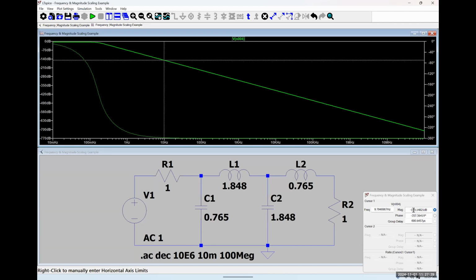So we're going to talk about Butterworth filters, which are used in applications where we don't necessarily want high Q, we want a very flat pass band. We're also going to talk about Chebyshev filters, which give us high Q, but introduce ripple in the passband that we have to talk about. We may have time to talk about Bessel filters as well, but then there's also elliptical.